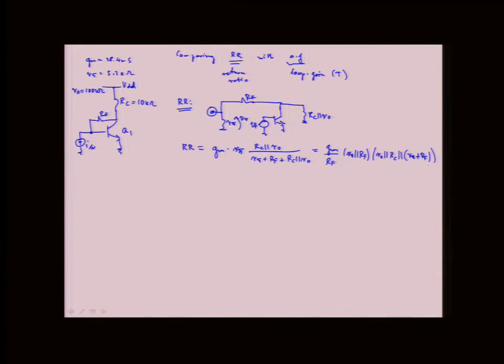Yep. That's a great point. So by definition, return ratio is minus VR over VT. Right. So if I did VR over VT, then that would be negative because I have a pi phase shift here, right? But because of this minus sign, it's actually positive. Okay, so return ratio from here, if we just plug in the numbers, would be 119. You just keep that number.